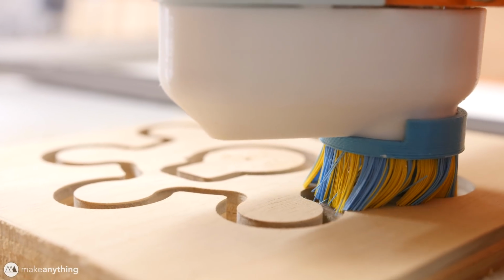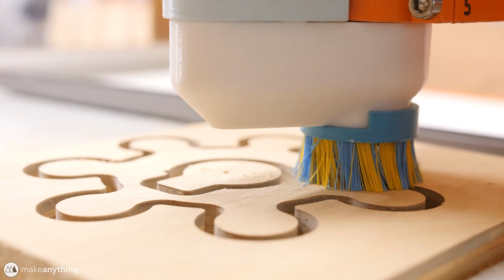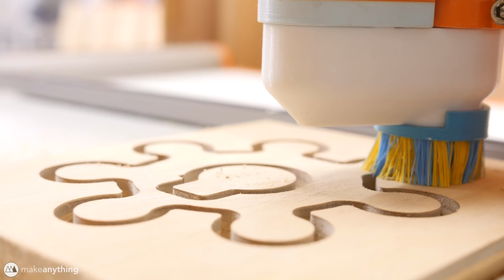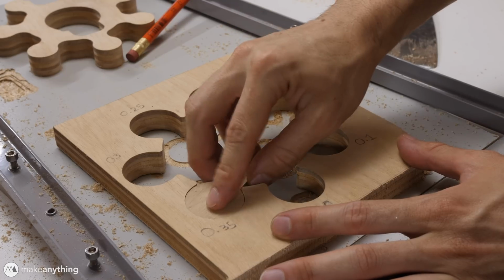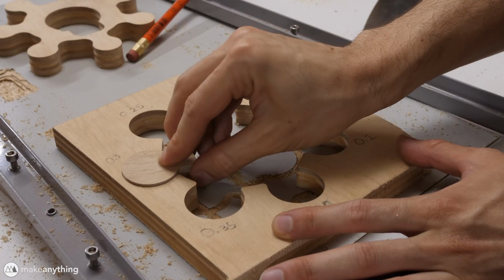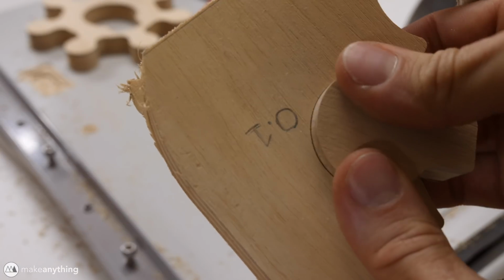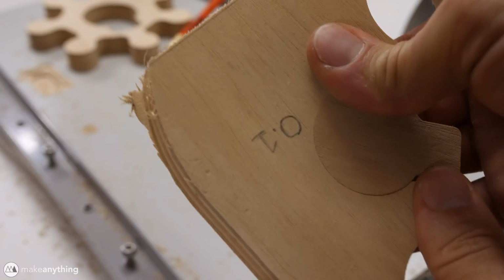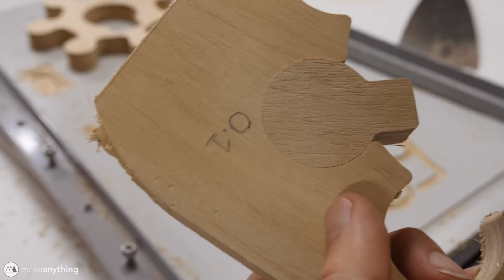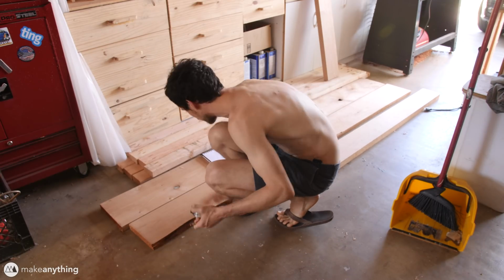I also decided to do one more test print, and this is a little tolerance test that I created, which basically has a little key and several different holes, each with a different amount of clearance, from 0 millimeters to 0.35 millimeters. I tested each of them out and discovered that a 0.1 millimeter clearance is exactly what I need to create a really nice tight fit. So that's what I'm going to use for now whenever I need to create two parts that slide in and fit perfectly together.